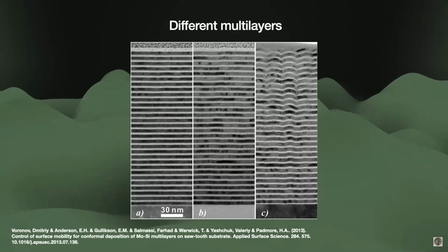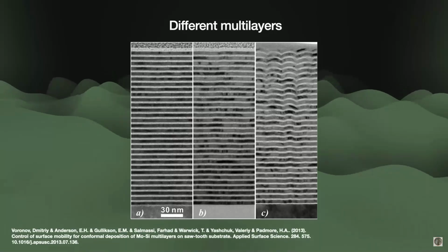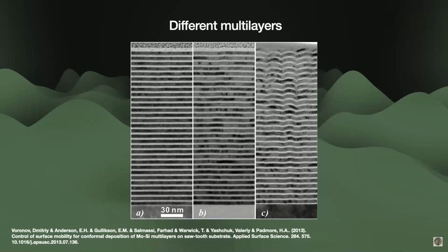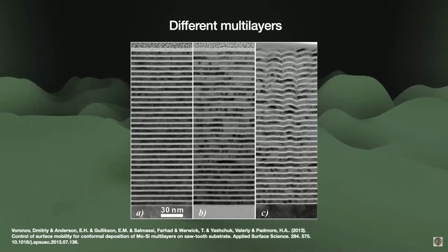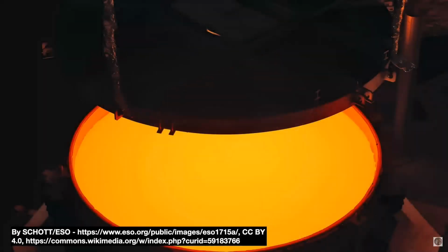As I implied earlier, the mirror heats up during exposure, but even just a few Kelvin difference can cause the substrate to expand and distort the mirror if it is made from the wrong material. Early EUV mirror substrates were glass ceramics like Zerodur or Clearceram, or special titanium-doped fused silica like ULE, ultra low expansion glass. Both substrates have their pluses and minuses. Ceramics might not respond consistently to polishing methods. ULE, on the other hand, suffers striations, material inconsistencies in the glass that affect its light refraction indices.